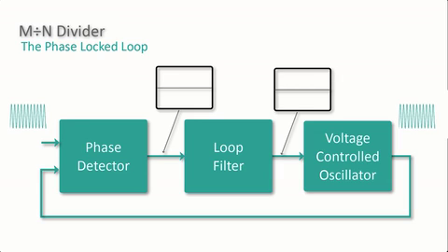Okay, now let's say that the input frequency begins to drift higher. The phase detector will begin generating positive pulses toward the low-pass filter. The filter will smooth and average these pulses to a rippling positive DC level, forcing the VCO to run faster until the input frequency and the VCO are once again in phase at the same frequency. The system is still stable, and the loop can still be said to be locked.